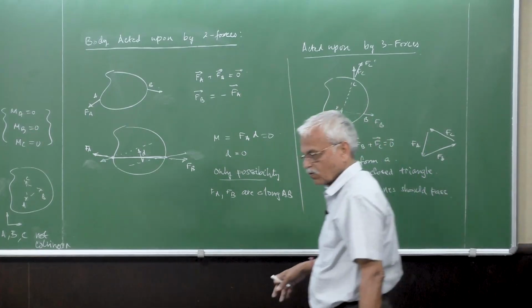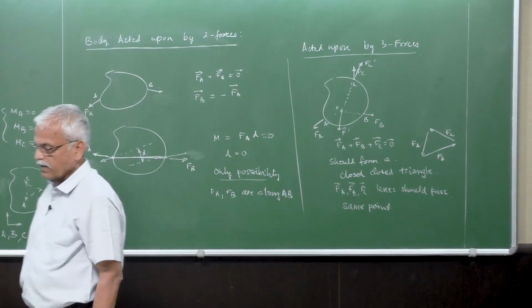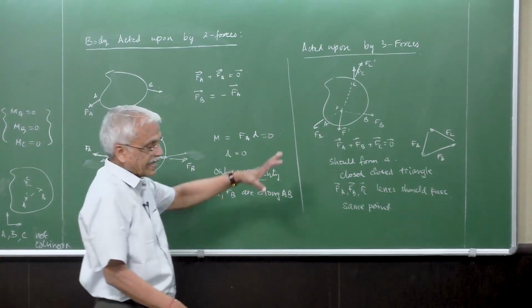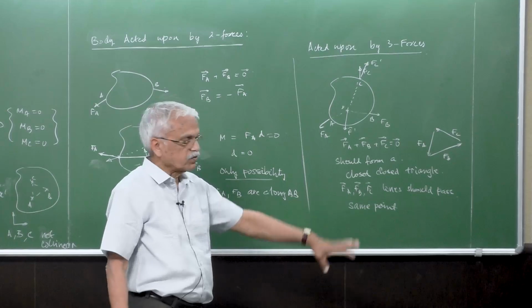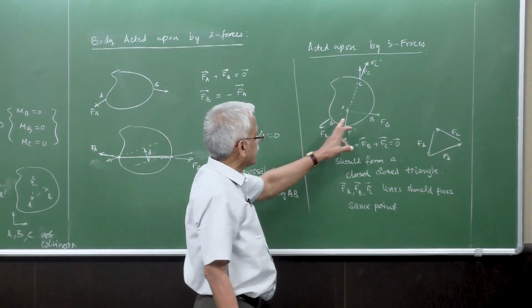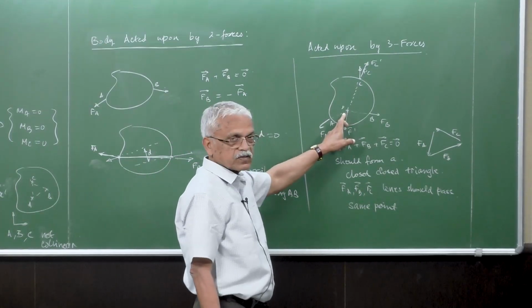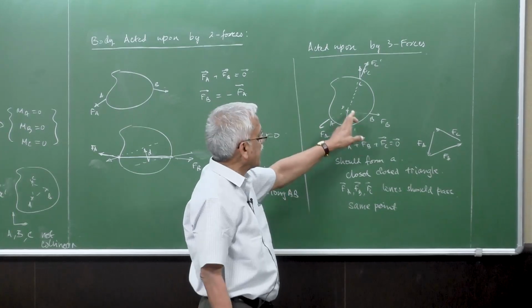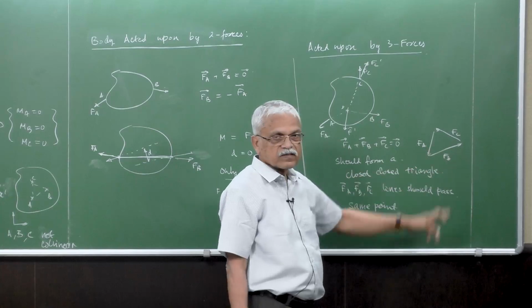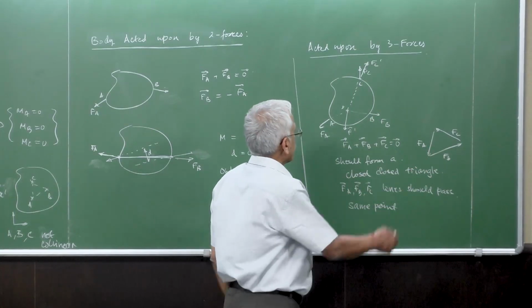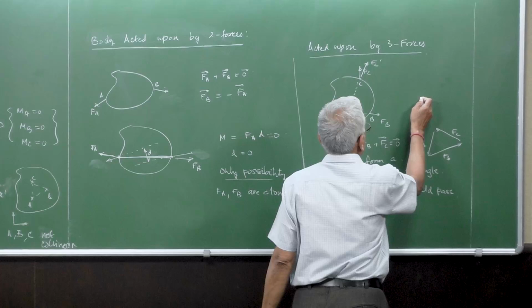So this throws up an interesting fact for calculation. If you know that there are only three forces, we know that they should pass through the same point, and further, for the sake of calculations, you can say that they should form a triangle.